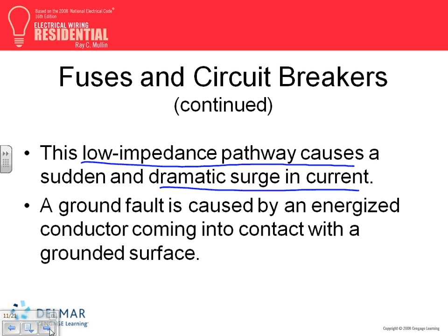If it's an electronic breaker, there's a sensor around the conductor. It senses the current. If the current is supposed to be 100 amp here, and all of a sudden it reaches 20,000 amp, that sensor takes the signal directly into the brain of the circuit breaker, which initiates a signal to the contacts to open immediately or with delay. So it's really sensing the current and making a decision.